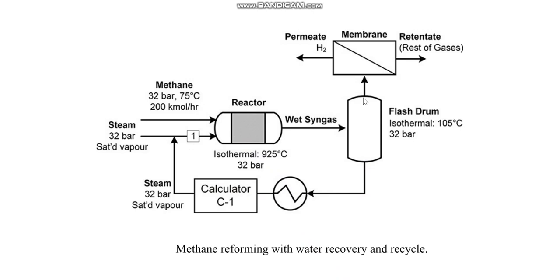And the top stream contains the gases, hydrogen, carbon monoxide, the CH4, methane, and some water vapors. This stream is passed through a hydrogen-selective membrane. So at the permeate, we get mostly hydrogen. This is like 90% pure hydrogen, and the rest of the gases are obtained as retentate.